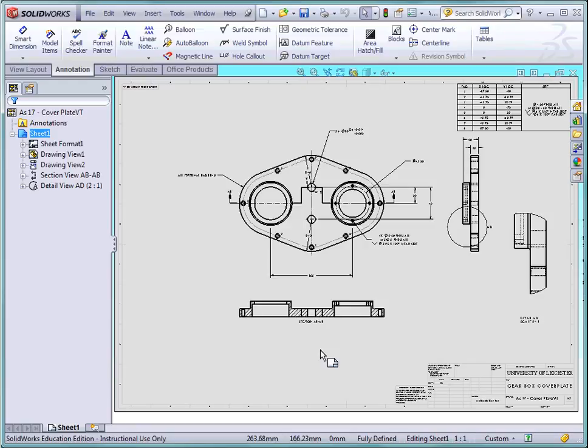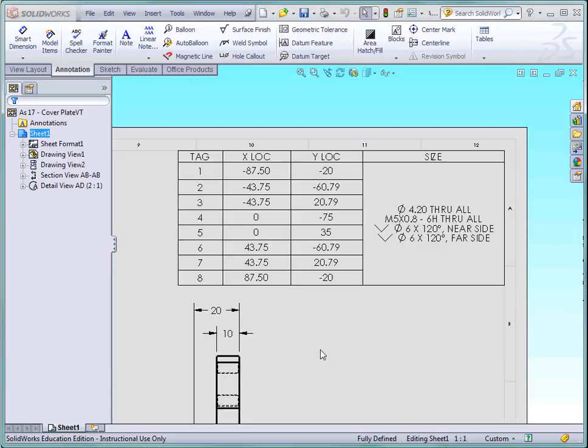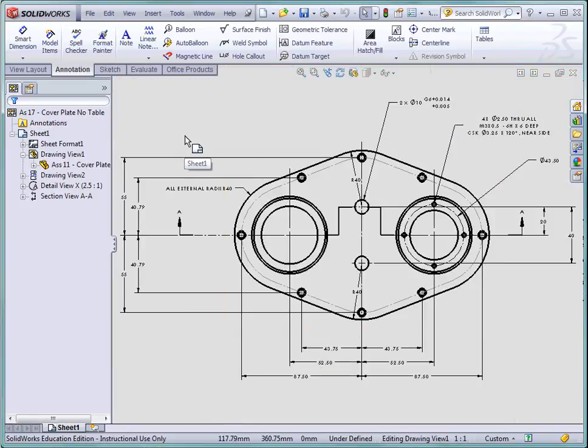Comparing this drawing with one conventionally dimensioned, there is little difference in drawing clarity. Where a drawing will benefit from the inclusion of a hole table is when there are multiple patterns of different types of hole. Another advantage of a hole table is in components manufacture. Mistakes are less likely to be made when hole positions can be clearly seen in a tabular form.